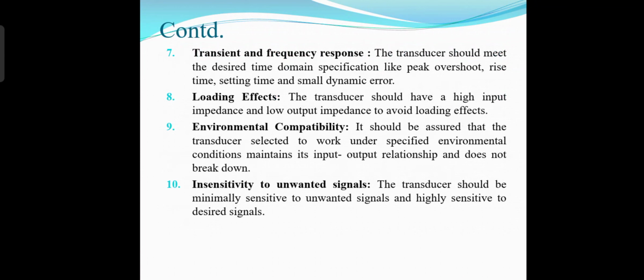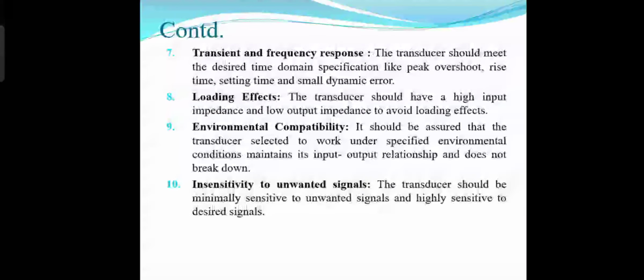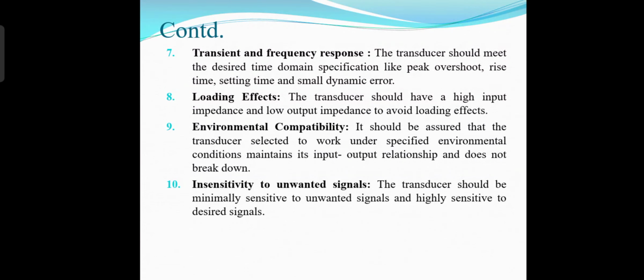Next is about transient and frequency response. The transducer should meet the desired time domain specifications like peak overshoot, rise time, settling time and small dynamic errors. Loading effect: the transducer should have a high input impedance and a low output impedance to avoid the loading effect.